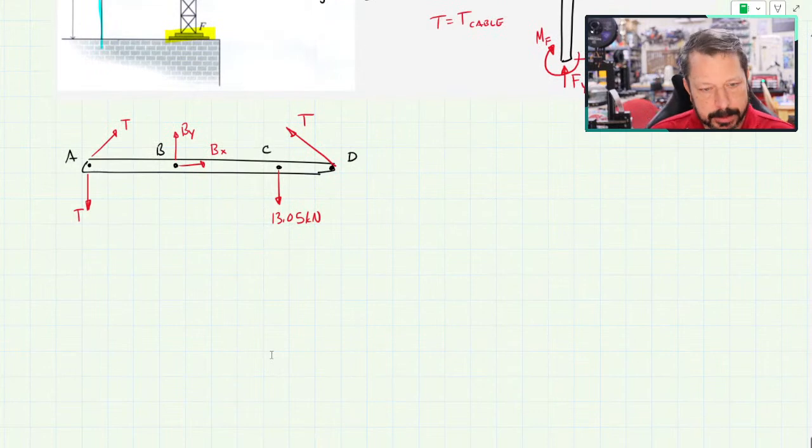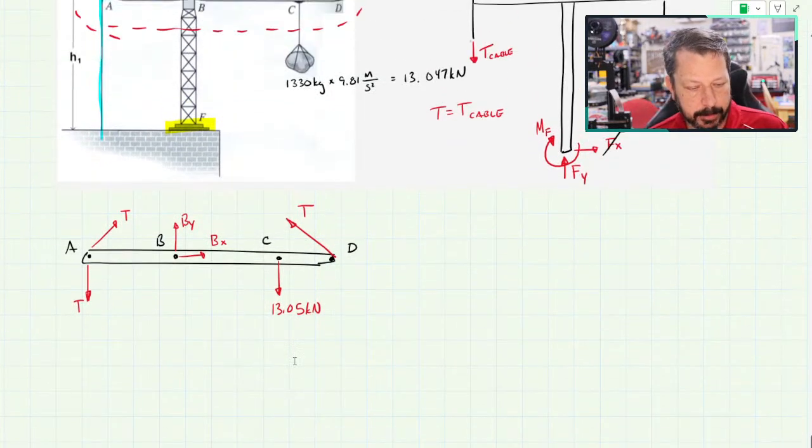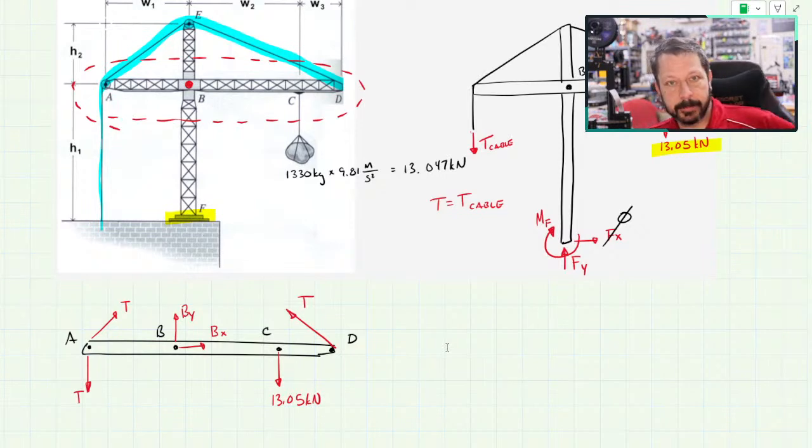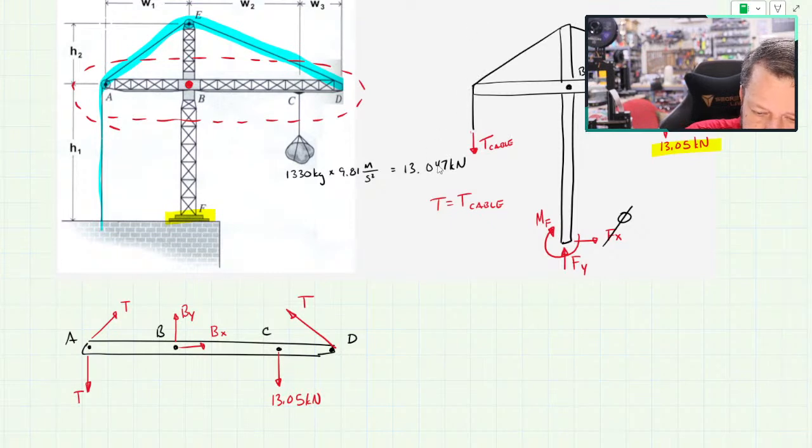Now, it would have some dimensions and things like that. Why don't we start putting those in? But here, it looks like I've got a bunch of unknowns. Like there's 1, 2, 3, 4, 5 arrows that don't have values, but 3 of them are all T. So they're all the same. So I really only have 3 unknowns. So I can work with 3 unknowns if it's not a concurrent force system, which it's not. So I can solve these. I just need the dimensions on there to be able to do anything. So let's see what our dimensions are.